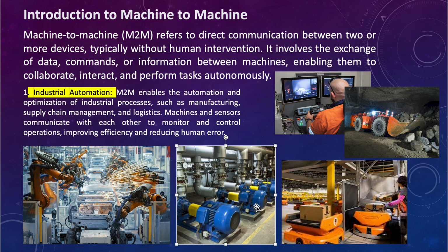Still it will not be enough, then motor 3 will automatically switch on, but then it will find out the pressure levels are now coming to normal, so only half the capacity is needed from pump number 3. Only pump number 1 and pump number 2 need to work at their maximum capacity.